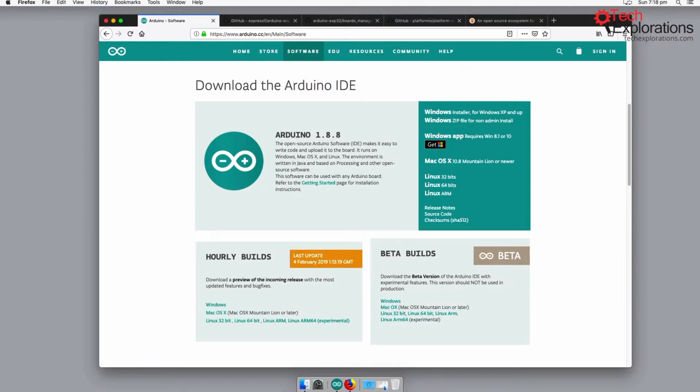And the first thing that we need to do in order to be able to do such work is to install the ESP32 support for the Arduino IDE. And that's what we do in this lecture. I'll show you how to provide the ESP32 support for the Arduino IDE first on the Mac, and then in the next lecture in Windows.